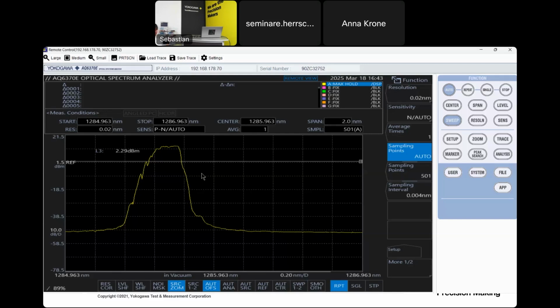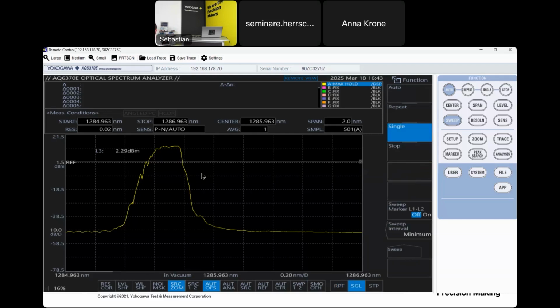In this mode, the minimum pulse width that can be completely measured is 100 microseconds. If we then go to the other settings for pulse light measurements, we can even detect pulses down to 50 microseconds. And for this, we will use the external trigger mode.